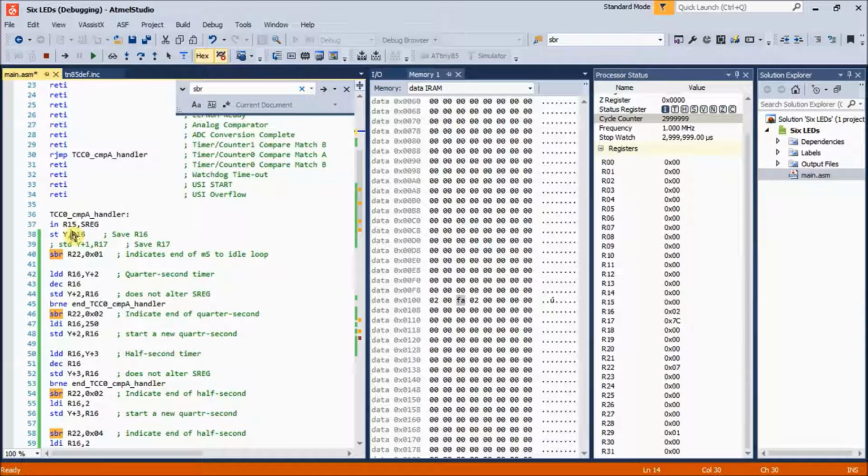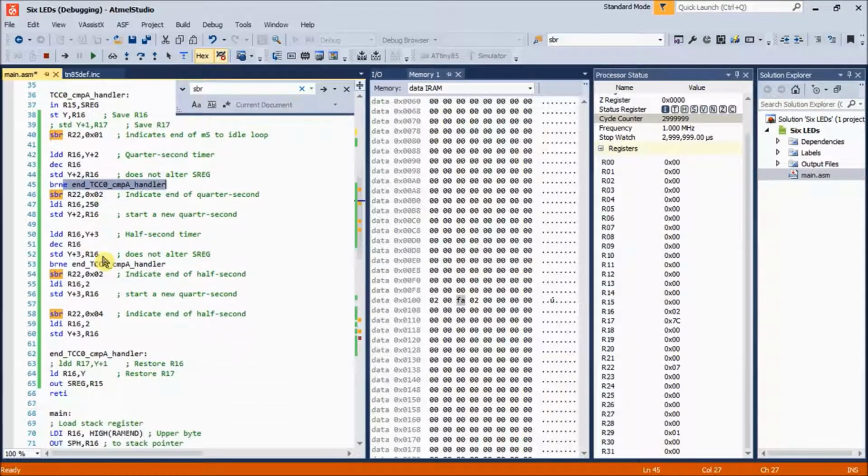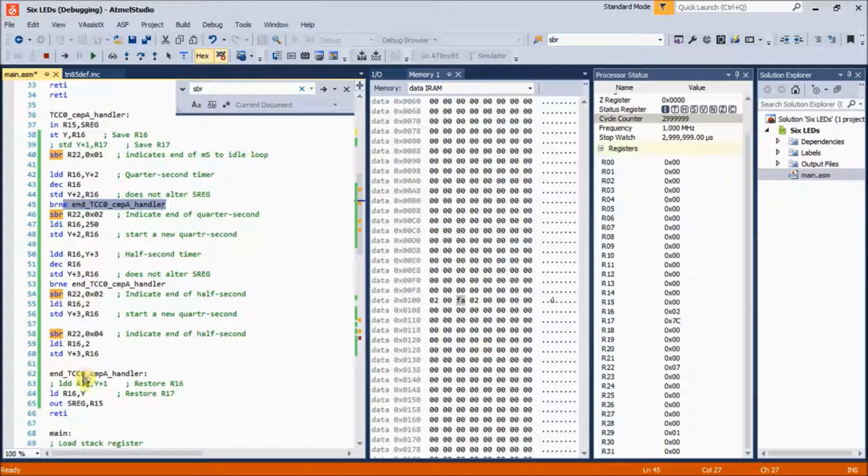Now, most of the time, remember, it hits this routine every millisecond. It's got to hit it 256 times before it fails to do a branch not equals to the end of the routine here. So the very worst case of this is where it executes all of the instructions in here, and that's going to happen when we have a 0, 1 in there and a 0, 1 in there. So when these are both going to decrement to 0, it should execute all instructions in the routine.